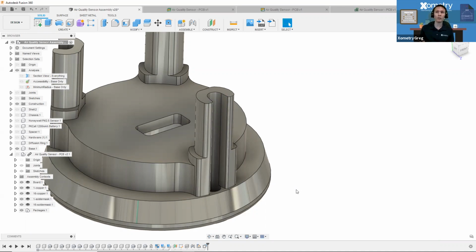And so again, at quantity one and prototyping, all right, that's good. It's going to be a more expensive CNC part. But if you're like, hey, it's time to make 600 or time to make 6,000, I may raise my hand and say, listen, if you don't need this U-shape and you can make it a boss, so like a drill through hole, it's going to save a lot of time. And when you're talking about making parts into production, time on the machine is going to be driving that cost. So it's going to reduce machine time. It's going to reduce the cost of that part. So yeah, if you could turn that into a full boss, I think it'd be great.